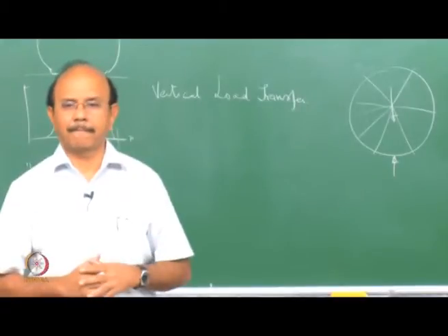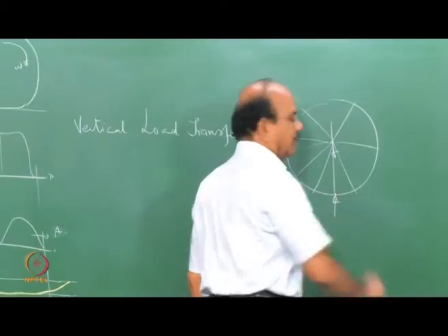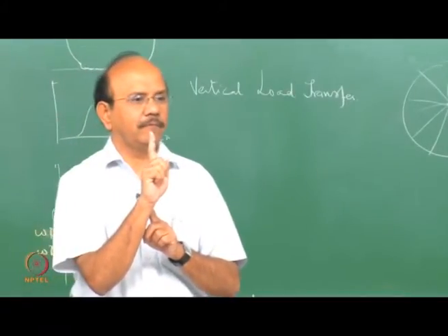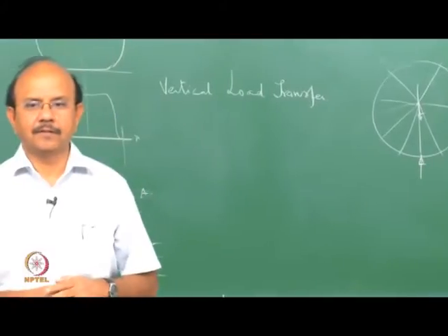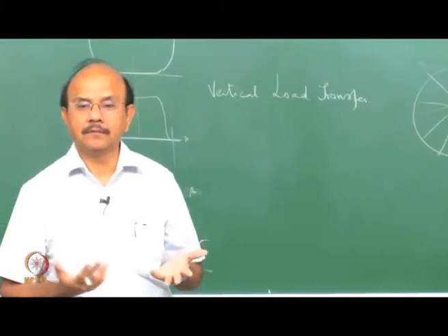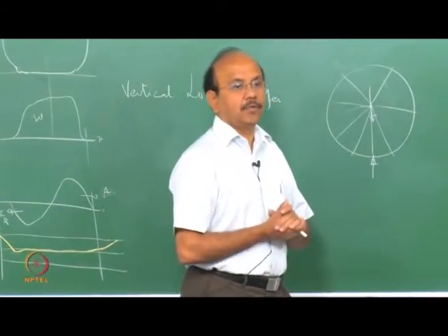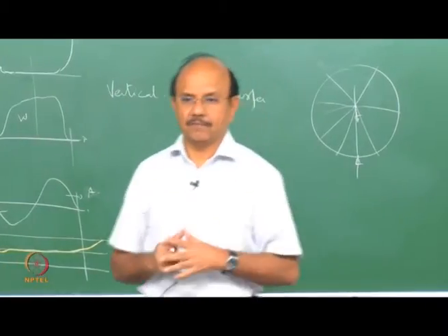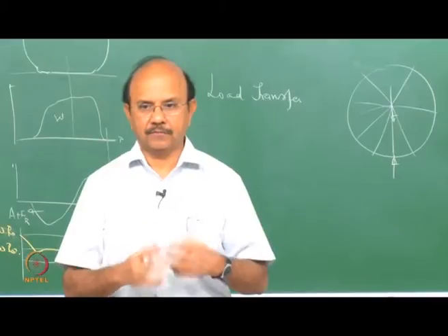Unfortunately, a lot more, because the spokes, as you know, are very thin pieces of steel. If you subject that spoke to compression, what is going to take place? It's going to buckle. So the spokes are assembled with tension. They are actually going to be assembled with tension.